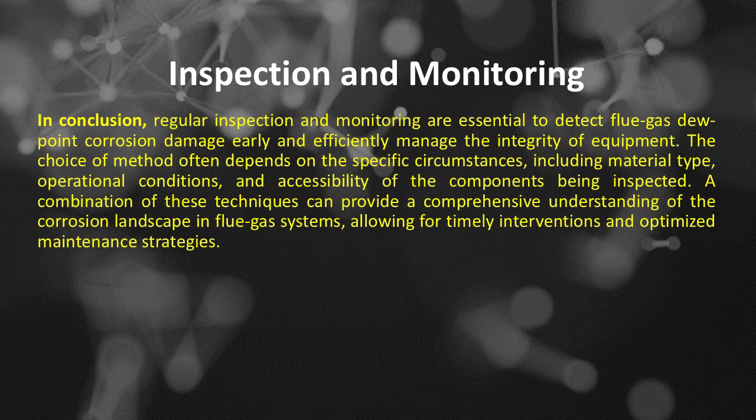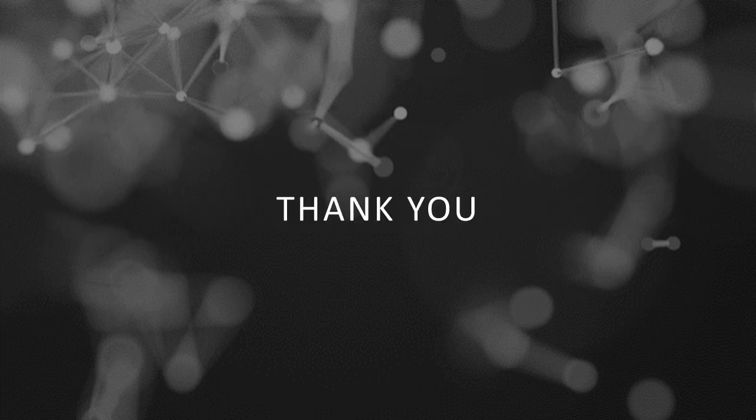In conclusion, regular inspection and monitoring are essential to detect flue gas dew point corrosion damage early and efficiently manage the integrity of equipment. The choice of method often depends on the specific circumstances, including material type, operational conditions, and accessibility of the components being inspected. A combination of these techniques can provide a comprehensive understanding of the corrosion landscape in flue gas systems, allowing for timely interventions and optimized maintenance strategies.